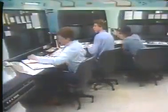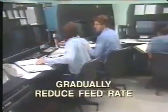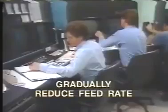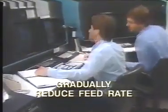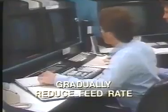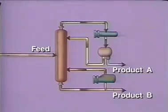The first step in most planned shutdown operations is to gradually reduce the feed rate into the column. As we reduce the amount of material put in the tower, the product output also decreases. By making gradual feed rate changes, the tower instrumentation can maintain the design conditions inside the column. This allows us to produce on-specification products while the feed rate is being reduced. The feed rate is reduced until the tower is on total reflux.